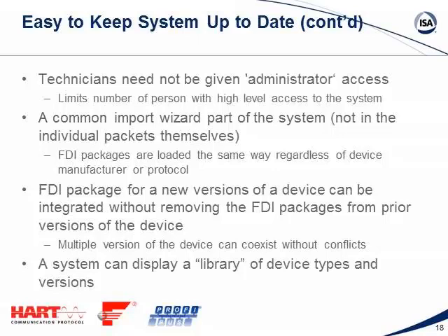That helps. A common software import wizard as part of the system can help you to handle those FDI packages, and those are loaded the same way regardless of device manufacturer. That means multi-vendor, don't care; even different communication systems, don't care. They are working: HART, Fieldbus Foundation, PROFIBUS, Profinet, whatever. An FDI package for a new version of a device can be integrated without removing the FDI packages from prior versions of the device. Multiple versions of the device can coexist without conflict.